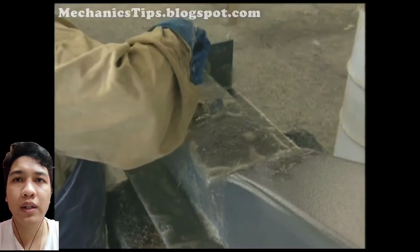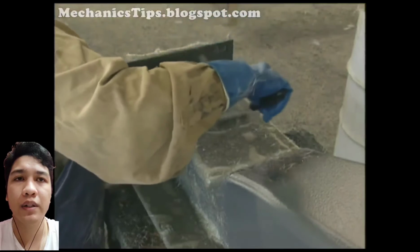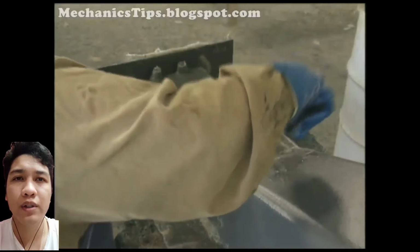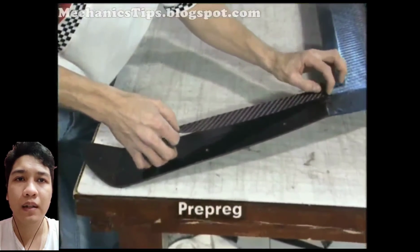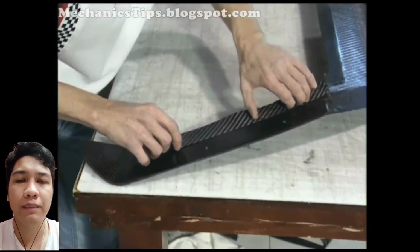This so-called wet layup method can be used with nearly all reinforcement materials and is widely used to produce glass reinforced polyester products and sometimes glass reinforced epoxy products. Wet layup is also used for making composite molds. Layup can also be performed using pre-preg material.